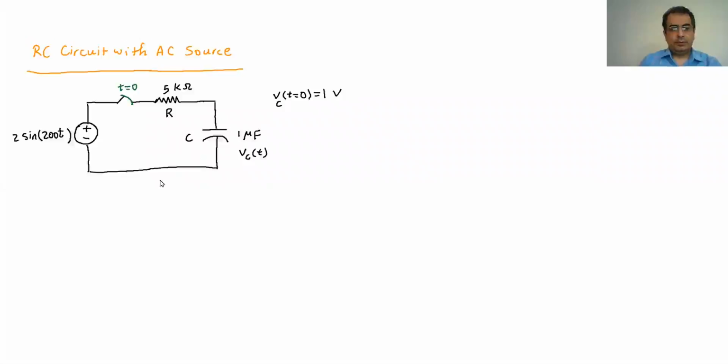First of all, the very first step is that we have to find the differential equation that describes the condition in our circuit. Assuming our circuit, the current goes through a single loop. So I can go ahead and write the KVL for this loop.